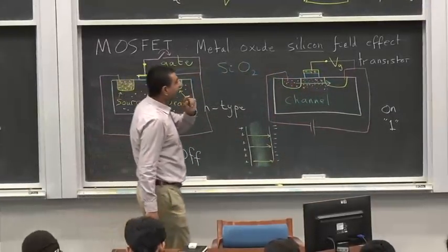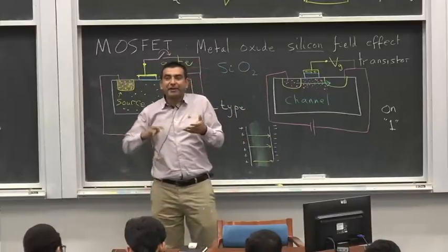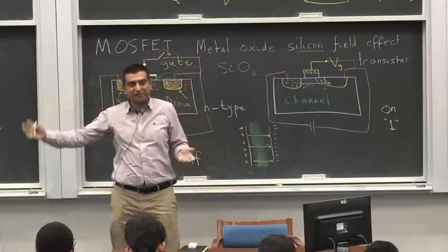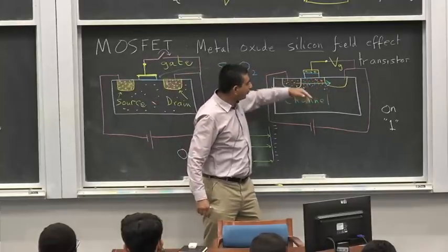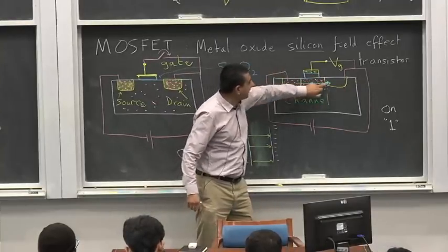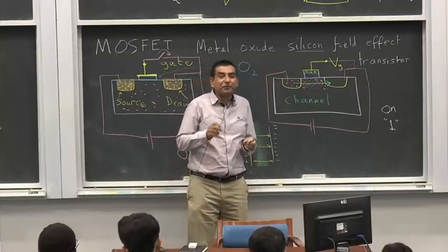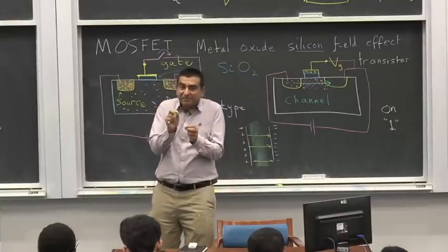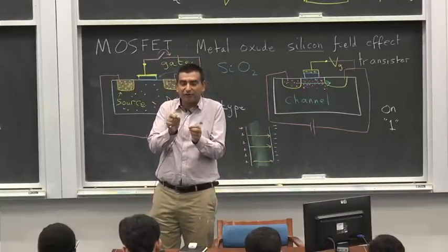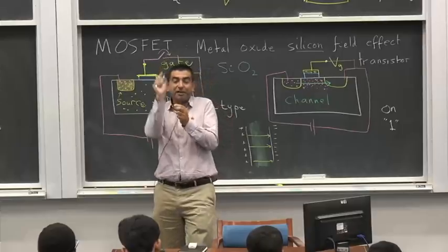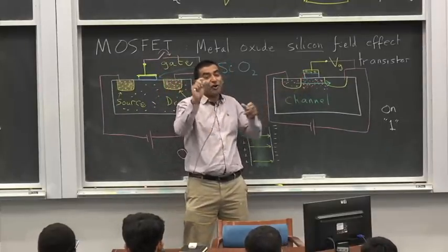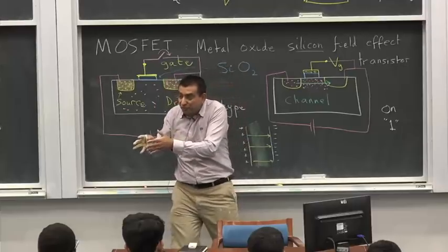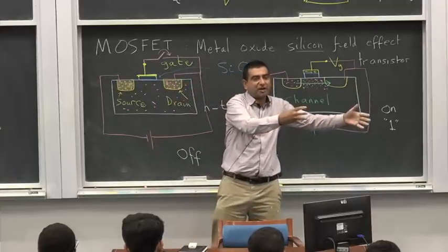The key idea is that you would like to reduce the power requirement of this transistor, which means you would like a large current to flow here. Those charge carriers come from the metal and the semiconductor, but you would like to have a small trigger between on and off. Please pay attention. You need a small trigger, which means you need only a few charges on the gate to actually control the flow of a large number of charge carriers.